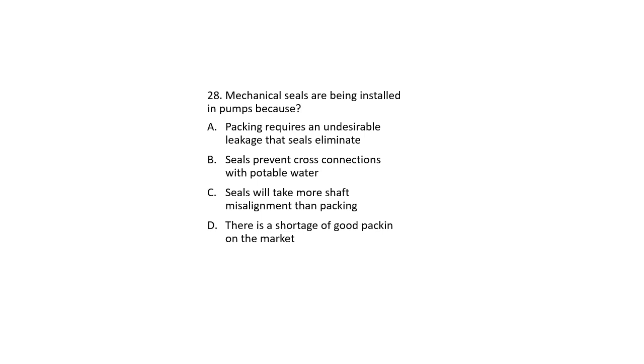Mechanical seals are being installed in pumps because packing requires an undesirable amount of leakage that the seals will eliminate. Seals prevent cross connections with potable water. Seals will take more shaft misalignment than packing, or there is a shortage of good packing on the market. The answer is A, packing requires an undesirable leakage. If you have a mechanical seal, you don't have to deal with that.